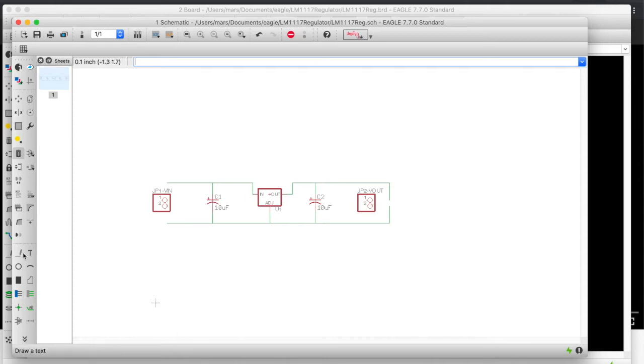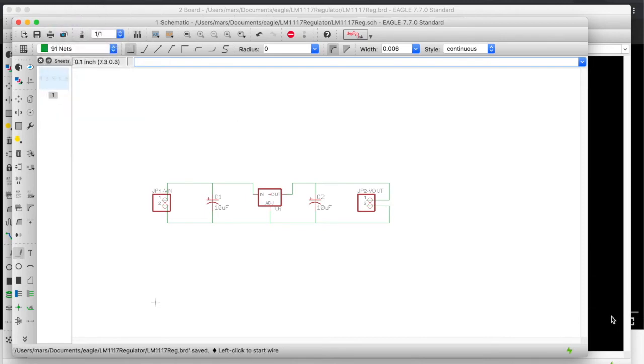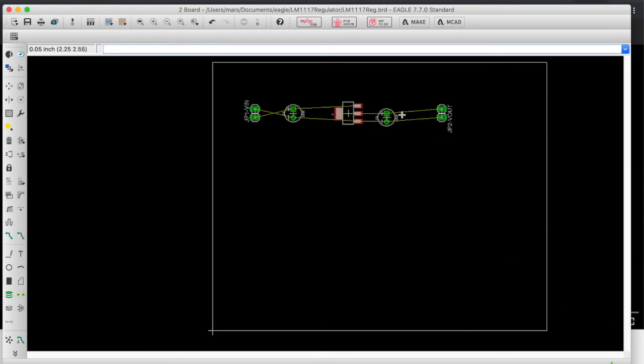Okay, so let's go ahead and make these connections again. What happened was, you can see that the circles where the connection should be made have this little red line on the left side. If the wire doesn't come off of that red terminal, the connection won't actually be made to the component. So make sure you go from the left side, and there you go. And now they're all connected. We save, it updates the board. And when we go to the board, there, our wires are there.